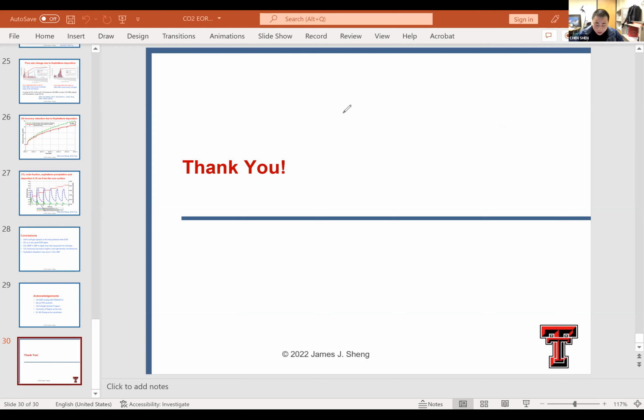Another question on our WeChat forum is for CO2 fracturing: how to inject the carbon dioxide into the well, and what the injection pressure is. Okay, how to inject CO2? CO2 is in liquid state. For a pilot test, we always have a tank, a truck to bring the liquid CO2.